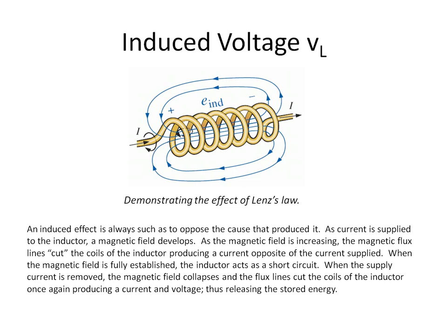Then, when the inductor's energy is sent back to the circuit because there's no power there to keep it charged up anymore, it's going to release its energy by that field collapsing down to 0. And as that field is collapsing, the lines of flux are going to be cutting the coils of the inductor, and therefore it's going to become a generator once again, releasing the energy back into the circuit.